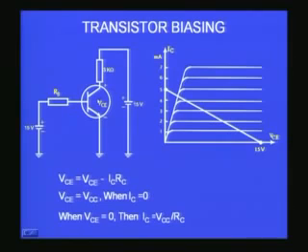The answer is indeed yes, you can do that, because you have the voltage and the RB. With this you can forward bias this base emitter junction and you can maintain your constant current. If necessary, you can vary these or choose a proper value of RB and VBB and you can maintain a constant current. And with the 15 volts here and the 3K, you would find that because there is forward biasing, there will be a current in the collector and the emitter, and therefore that will correspond to your voltage being developed across the collector and the emitter regions of the transistor. So, it is in principle possible to bias in the simplest way by using two power supplies and two resistors.